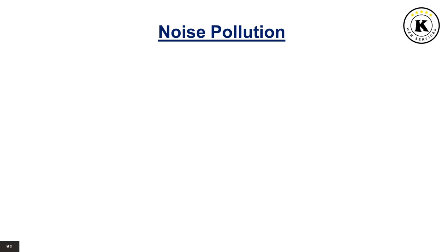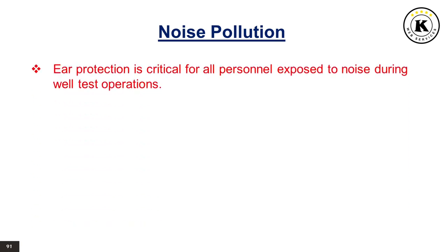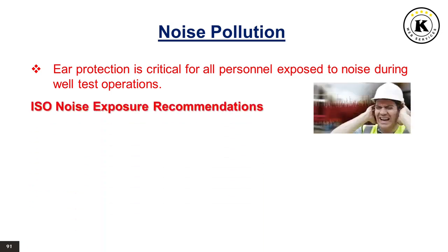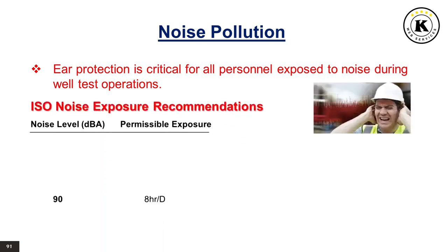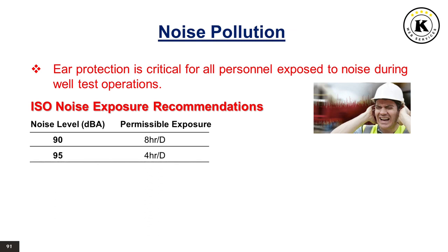Noise pollution. Ear protection is critical for all personnel exposed to noise during well test operations. According to the ISO noise exposure recommendations, at 90 decibel noise level, the permissible exposure is 8 hours per day. At 95 decibels, 4 hours per day.